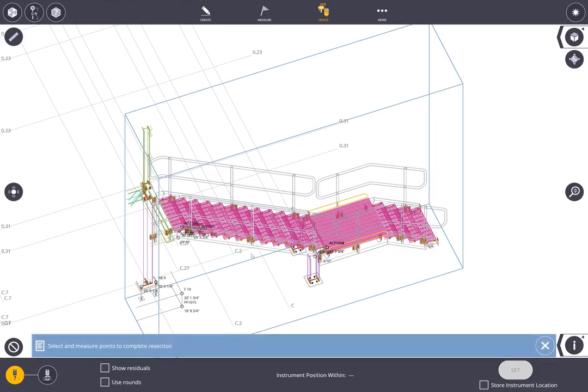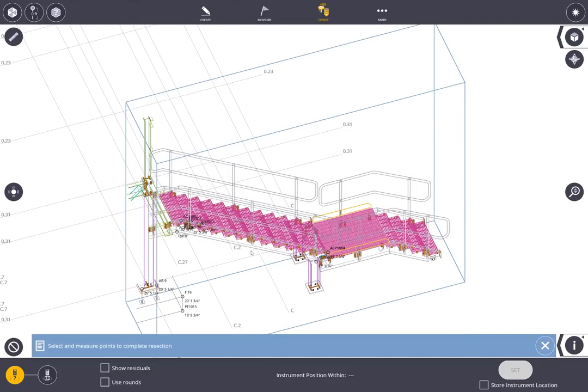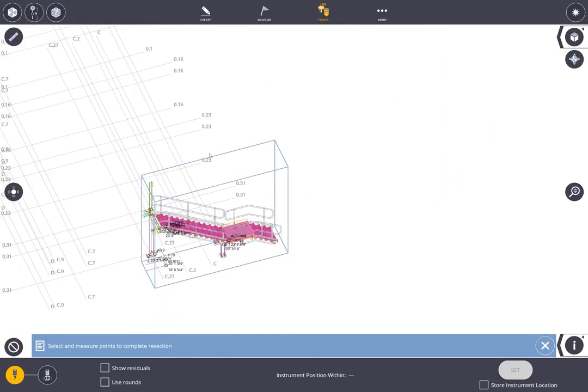So if we wanted to set this assembly up in the shop for fabrication, we'd actually come in here, and there's a couple different modes that we're showing right now in the emulator. So we have a setup anywhere. We could set the total station up on the project, maybe out here in the dirt. We could shoot 2 of the grid intersections, and it would triangulate the position of the robotic total station, and we could lay out the rest of the project from that location on site.